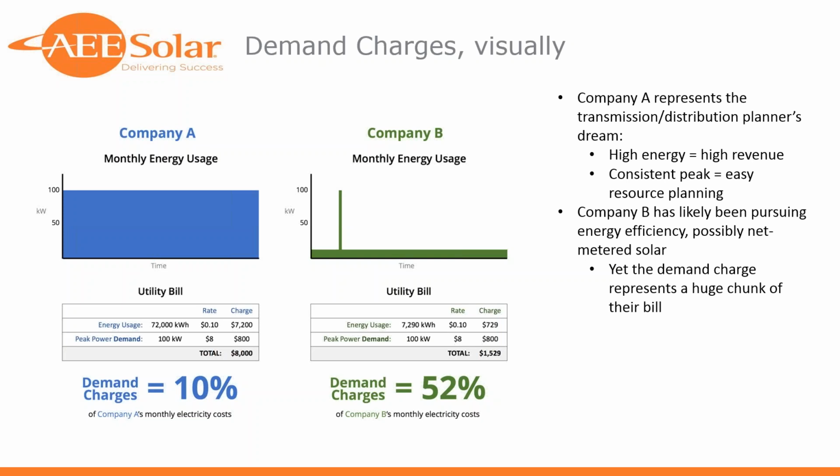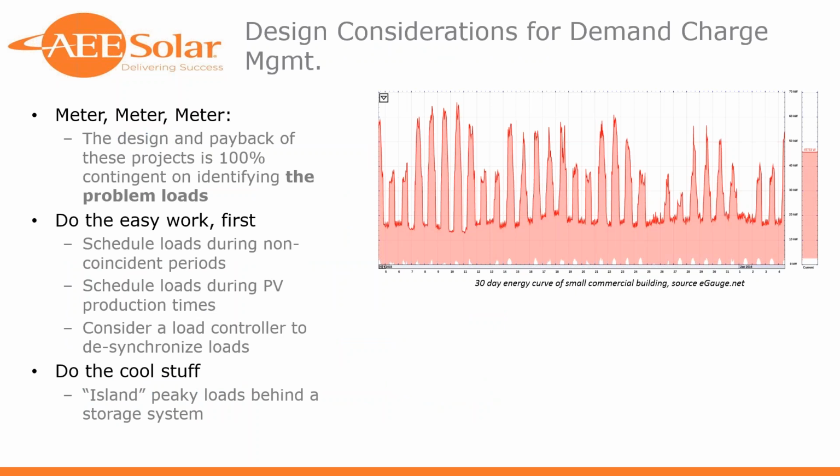So some design considerations for demand charge management. How do you go about even building out a bill of materials or designing a system? Really, it's going to start with meter. Just looking at a customer's utility bill is only going to give you half the story. That bill is going to tell you, at a high level, what proportion of their savings could be addressed by demand charge management. But it's not going to tell you